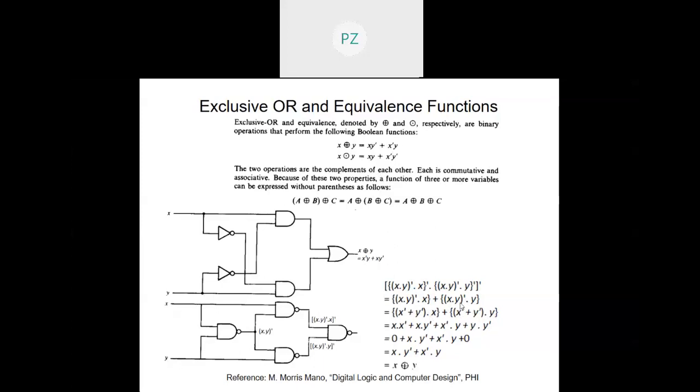So now in the next step, we will apply the distributive law. When I apply the distributive law, this becomes x' + xy'. Now over here it will be x'y + y', and we know that x' is 0. xy' will remain, x'y will remain, this will also be 0. So anything ORed with 0 will give me the same thing back. So it will be x·y' + x'y, and this is x exclusive OR with y. So using just 4 gates, I can realize an exclusive OR function.